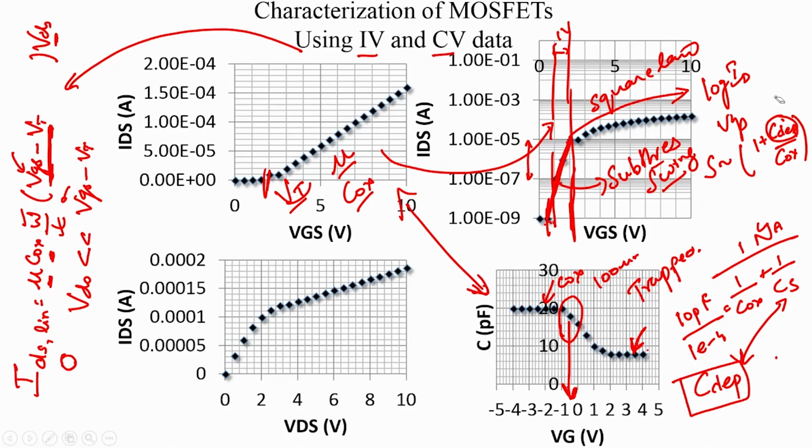And if there is a mismatch, it is possible that you have interfacial trap capacitance, and therefore, it is also a means to combine these two characteristics to extract the interfacial state capacitance, because the interfacial trap capacitance is less likely to respond at high frequencies. So, this is one useful parameter you can get from the log ID versus VGS characteristics.